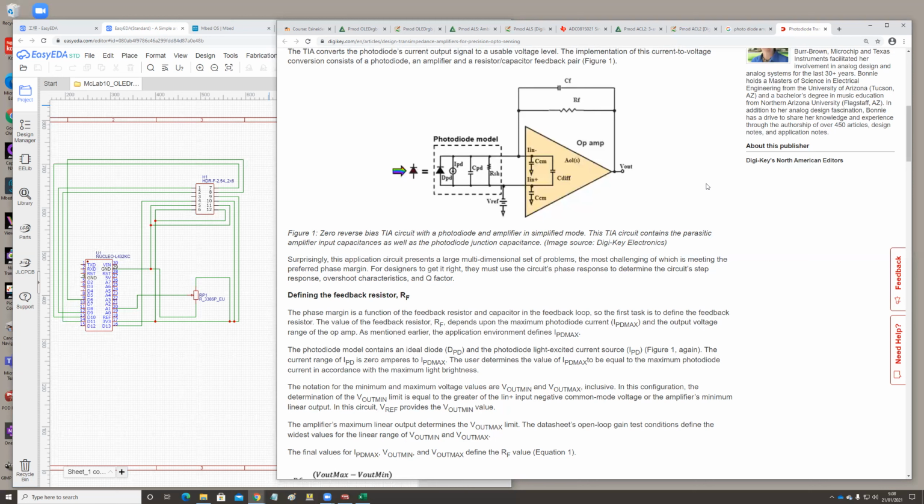But if you are measuring something like just a light in a room, and you do not like to take the flickering of the lamps into the measurement so that you get a stable value out of the measured light input, you put here a large capacitor, and then you get a stable output out of here. So with this capacitor, you define how well it is detecting the very fast changes of the light intensity, like it is needed in data communications.